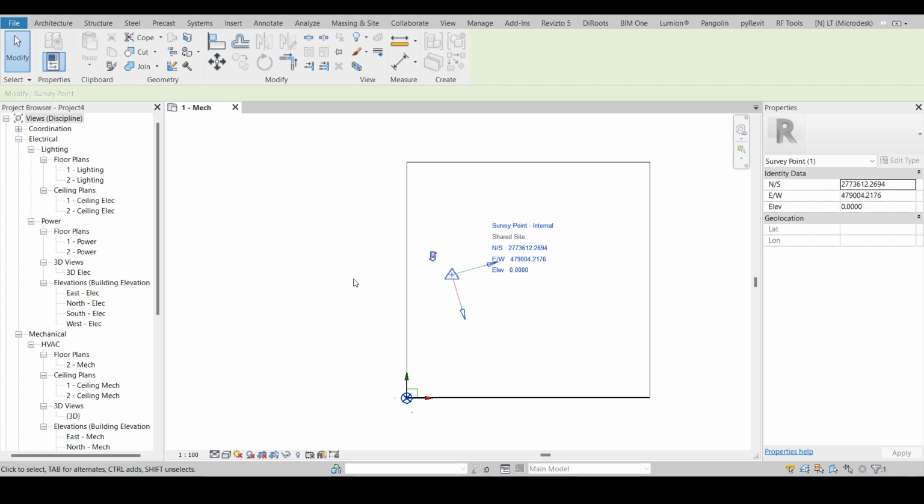That's why I told you, when you are setting up the file, there is an understanding gap with the person who is primarily setting the file. They should not make this mistake. Once they set up the project coordinates and project base point, they should move this point only after pinning and finding the other coordinates, and just leave any point here or here, not an issue. But they should not do this experiment. If they do this and you are following the correct one, then your file will not sit correctly. You understand? That's why these glitches are coming. So this is completely not your fault, it's an underlying file problem. But you need to know the reason.